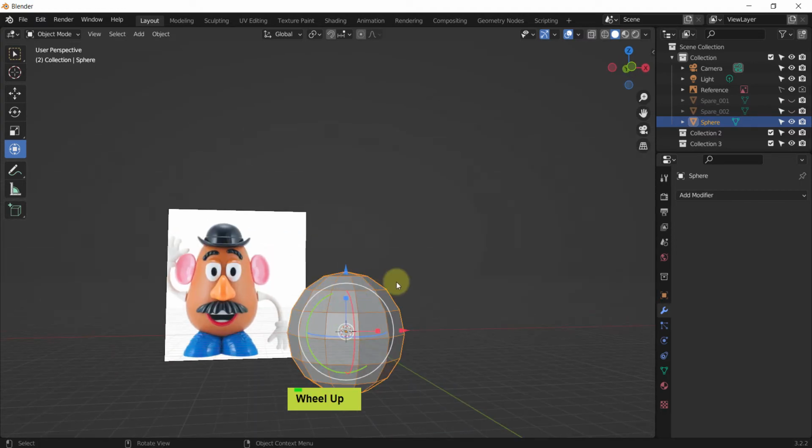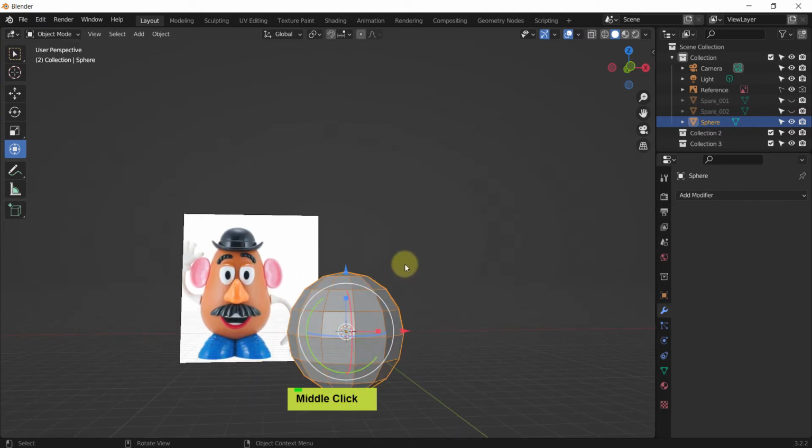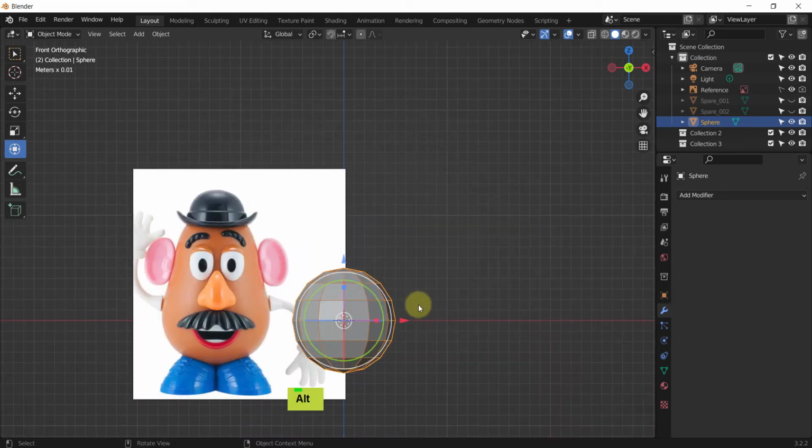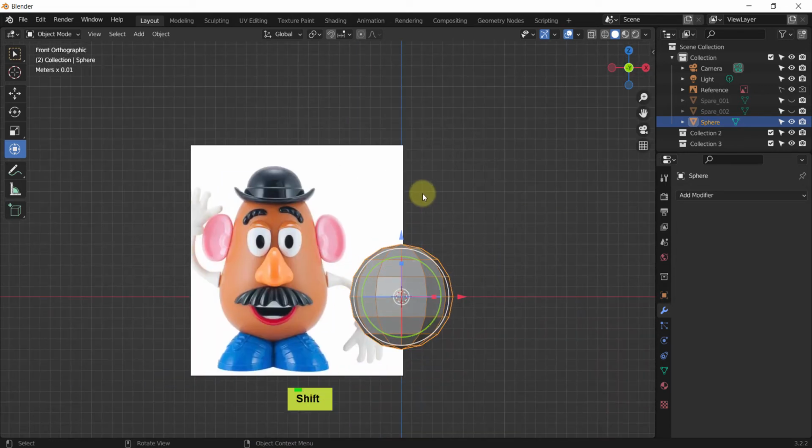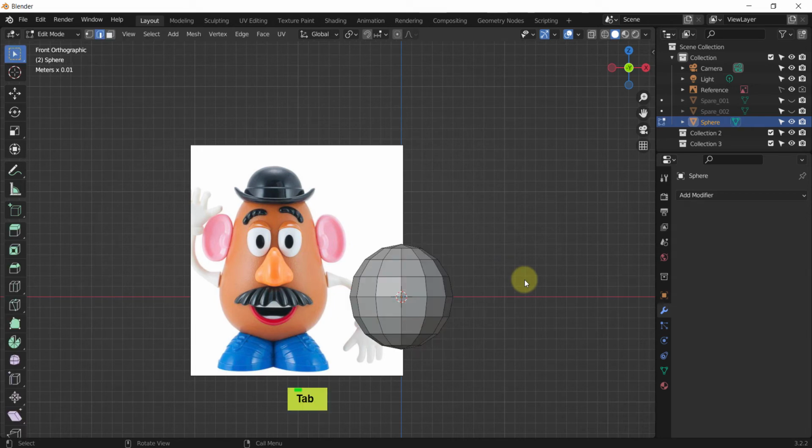We can move forward by creating the body. So the way we do it is going back to the front, and I want to stretch this out a bit. So to actually do that, I need more segments when it's once stretched out. So let me go into edit mode, and vertices will be just fine. And I want to B box select all the vertices in the top, but be careful, because if you're not in see-through mode, it won't select the back points. So for that, it's Alt Z, and now it's see-through.